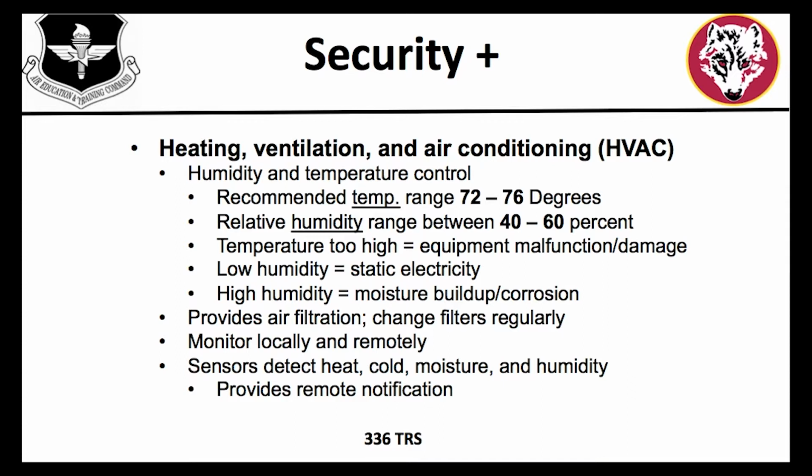So that room is going to be housing all of your servers, which are housed in locking cabinets or server racks. They produce a lot of heat. So you've got to have these very powerful air handler systems to generate a lot of cold air to keep it at a normal range. They're also going to be responsible for keeping the humidity in check. Now what we're looking at here, the relative humidity has a range between 40 and 60%. So your HVAC is going to be providing temperature control and humidity control.